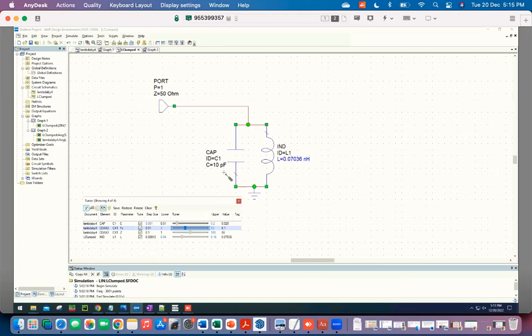So there was a constraint in the transmission line that I said the characteristic impedances can only go from 20 to 100, and that sets some limit on the effective capacitance and inductances you can get for your effective LC resonator. Here also in realistic terms, you cannot get arbitrarily large capacitors. I mean, you might say, yes, 1000 picofarad is available, but that at microwave frequency is not going to work, right? So you cannot have large capacitances and large inductances also, particularly even if you're using lumped element, making large capacitance and large inductance is very hard at microwave frequencies.